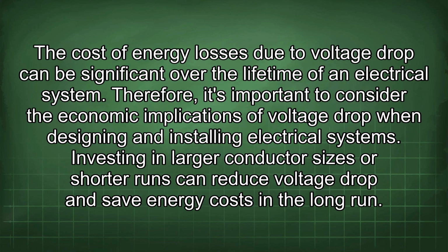The cost of energy losses due to voltage drop can be significant over the lifetime of an electrical system. Therefore, it's important to consider the economic implications of voltage drop when designing and installing electrical systems. Investing in larger conductor sizes or shorter runs can reduce voltage drop and save energy costs in the long run.